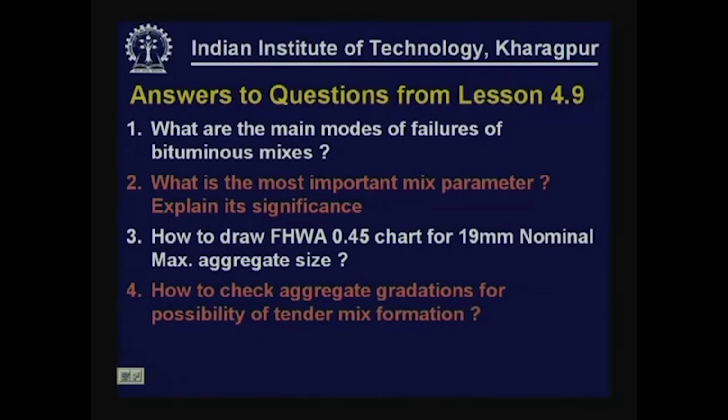Bituminous mixes normally fail in various modes, one of them being cracking of different types, cracking that can start from the bottom up, cracking that can start from the top down, caused by various reasons: repeated application of loads, climatic conditions, cyclic variation of thermal stresses. Various parameters can cause cracking of these mixes. So, cracking, either fatigue or other type of cracking,